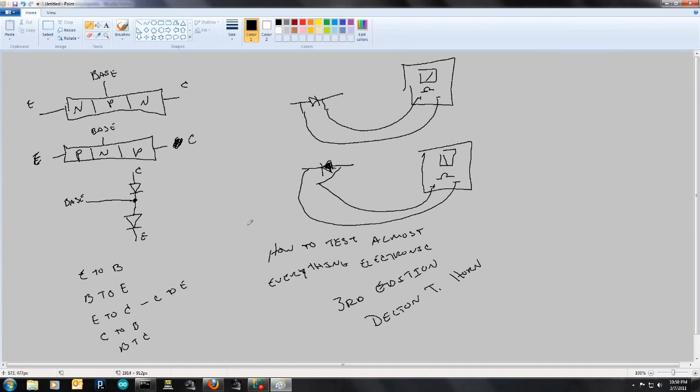And then the tutorial after that, I think we will do relays. Because we've learned how to control a little LED with our light sensor, but let's control something AC. And of course, when I do that video, I'm going to tell you don't do this, because working with AC is dangerous. But I'm going to do it, and I'm going to recommend that you don't do it, but I'm going to show you how you can do it. Just so you know. These microcontrollers that we use, their digital pins only supply like 20 milliamps. So basically, the only thing you're going to do is control either LEDs, or you control something else that controls LEDs, either an NPN or a PNP or a relay.